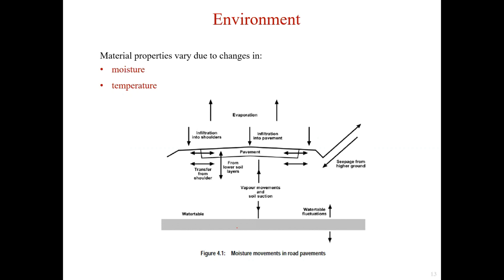Temperature may also affect the properties and performance of cemented layers and concrete. It could also have a significant effect on the rate of strength gain of these materials. And if high temperatures occur during construction, drying out will result, impairing both the ultimate strength and fatigue characteristics of the materials.